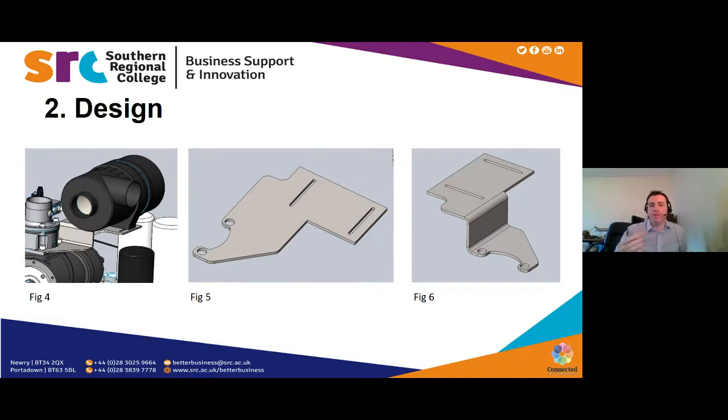My point here is that the way the air filter was going to be mounted before was to the side of the machine, which meant more steelwork and more complex bracketry. This part probably costs £5 to manufacture, where previously you were talking maybe around £12 to £15. So although it's a small saving, if you've got 10 or 20 parts, the savings soon add up.